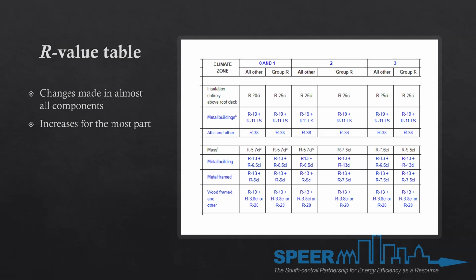All I can say is, if the building's big enough and you can use that heater that's going to meet the requirement to keep it from freezing, and the wattage and energy usage is low enough that the 3.4 BTUs or 1 watt per square foot limit is not exceeded, it's still considered non-conditioned building and doesn't have to comply. Once you've gone over that, all bets are off.